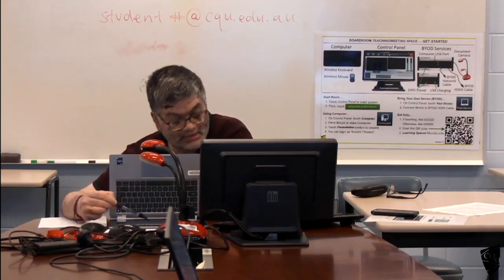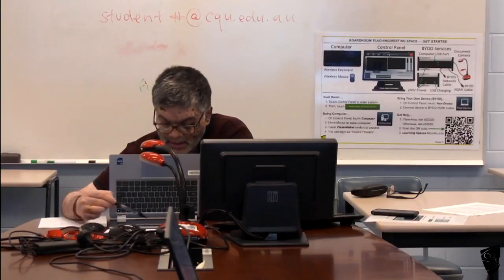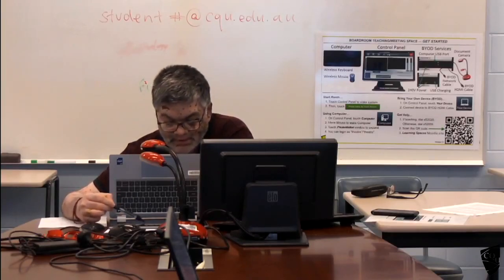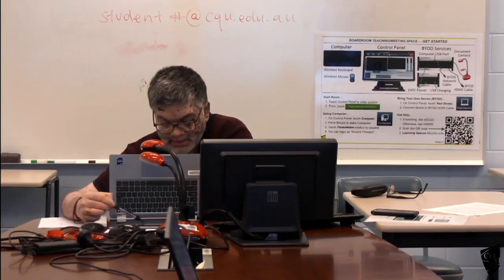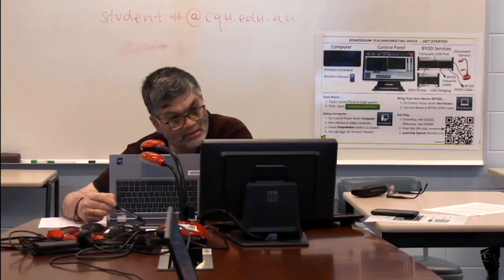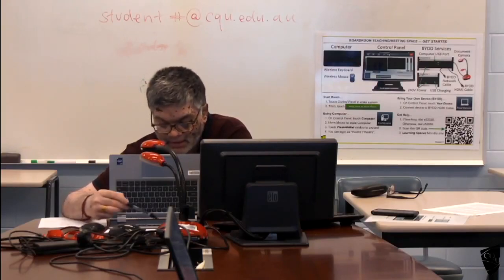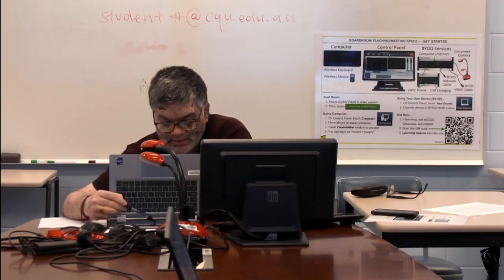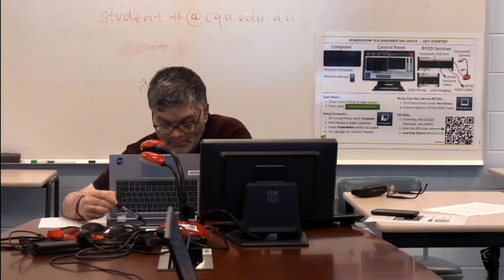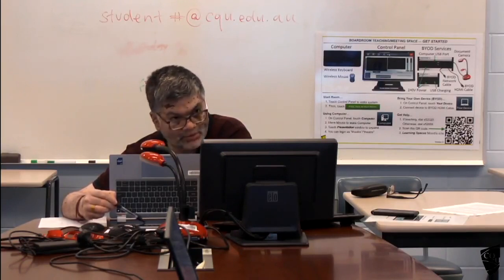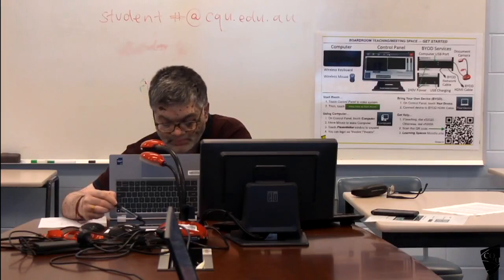For the strength limit, ultimate limit, from 60 to 100% will go to the column strip. So normally we will take the average of that, 0.6 and 1, the average is 0.8. So if you have a negative moment at the interior support, 80% will go to the column strip, the average of these two, and the other 20% will go to the middle strip.